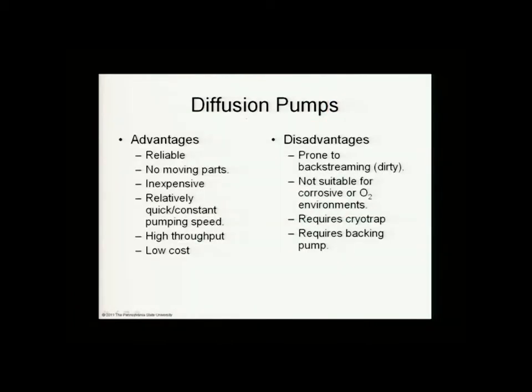Diffusion pumps have a number of advantages. They're reliable. They have no moving parts. We just saw there's nothing mechanical there. They're inexpensive. They're relatively quick, with a good pumping speed. They have high throughput. In other words, they can really handle a lot of gas and get it through the system. And they have low cost.